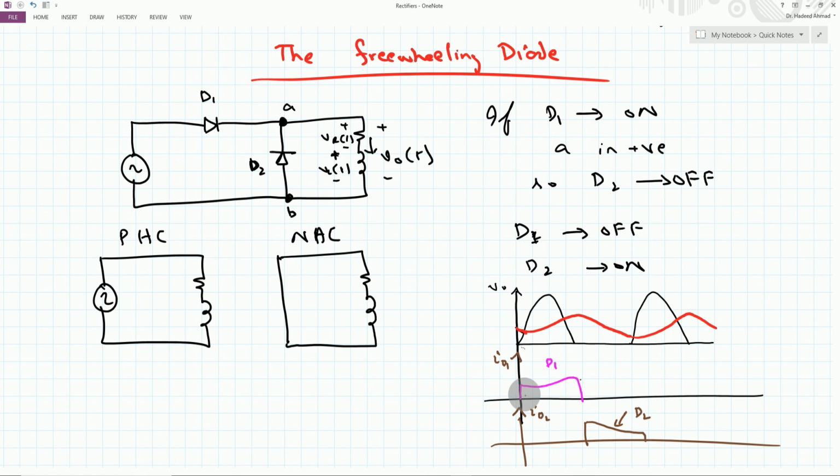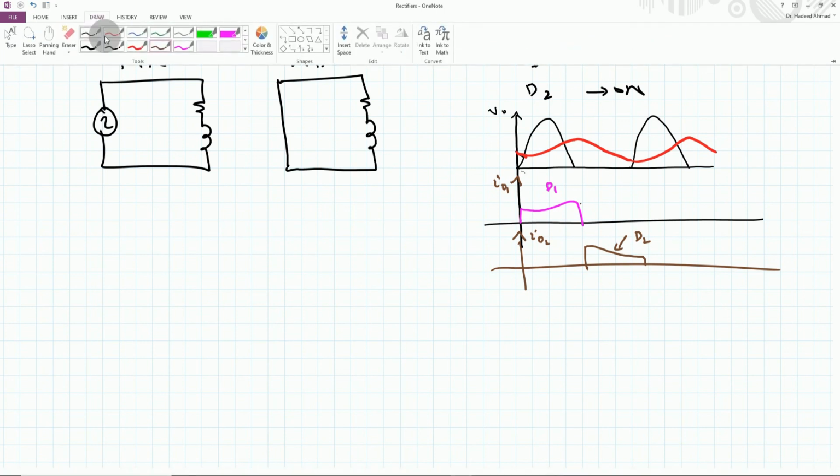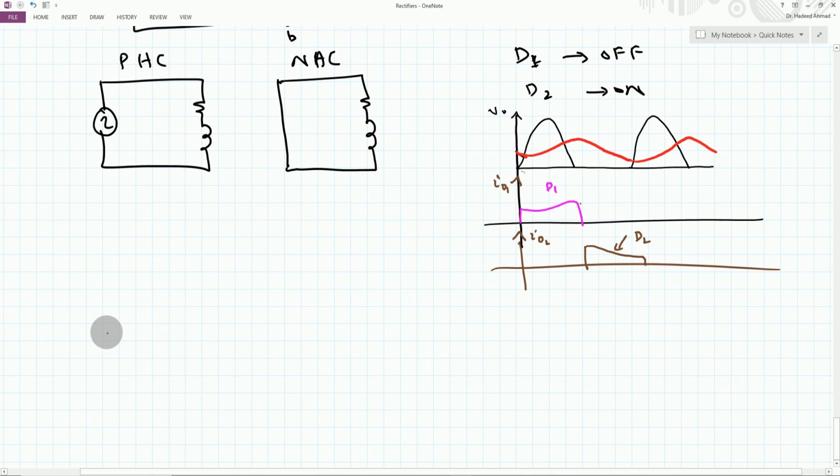Now if you notice one thing here, all of these half wave rectifiers have a sort of complex output voltage waveform and current waveform. Therefore the Fourier series is used to quantify the different harmonic contents present in a given system. You cannot find the value of the RMS voltage unless you have the information about the AC component flowing in these given waveforms.